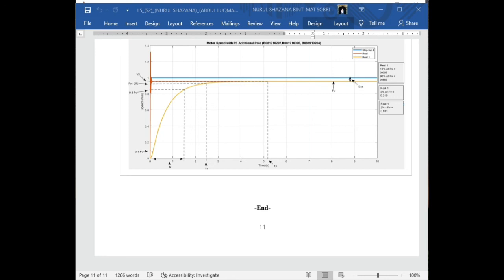The heat for the cooker comes from steam, so the steam valve is controlled with the overdamped response, so it is opened slowly and allows the temperature to increase slowly. It may take over an hour to bring the temperature from room temperature to 200 Fahrenheit.